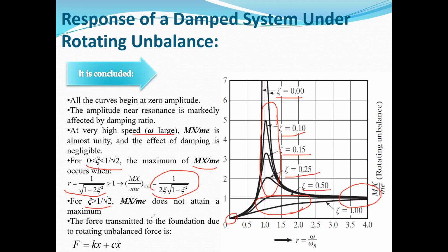And finally, the force transmitted to the foundation due to the rotating unbalance force is Kx plus Cx dot, where this x, in fact, is the response of your system, and it's similar to the force transmitted in the base excitation. Okay, any question from this part?